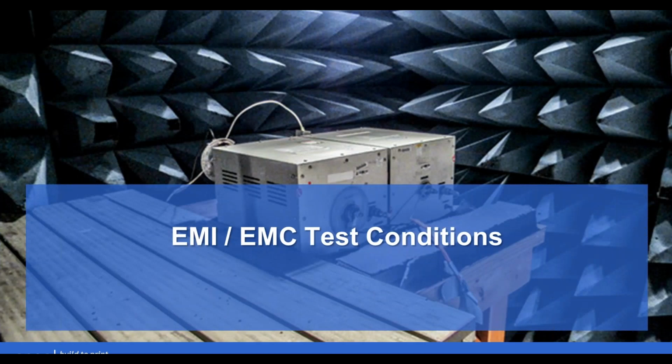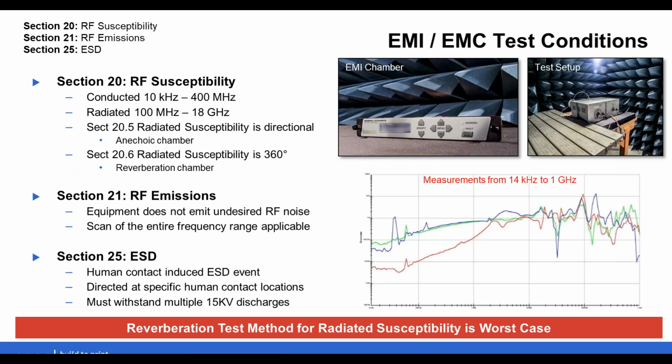Next, we're going to touch on some of the EMI and EMC test conditions within DO 160. And again, that's electromagnetic interference. So the 3 sections we're going to touch on today are section 20, 21, and 25 respectively, which is RF susceptibility, RF emissions, and ESD.